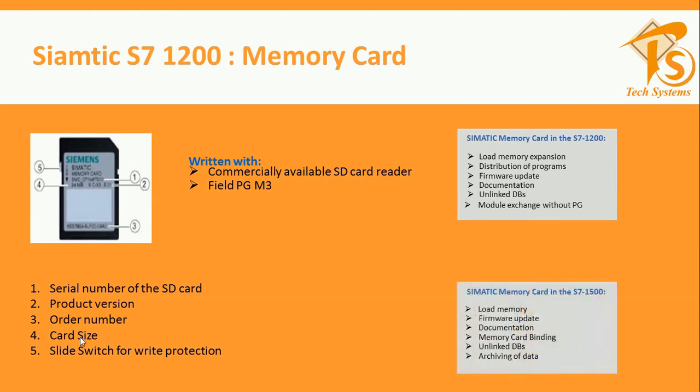For which purposes do we use it? The load memory extension, distribution of programs, firmware update, documentation, unlike DBs, and module exchange without PG. It means if one PLC is running and you upload the data from this PLC to the memory card, right now your memory card is in program mode.